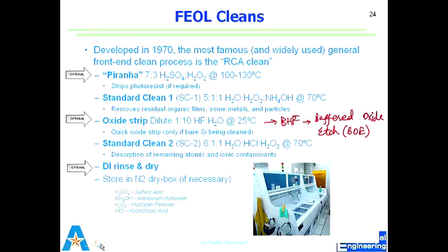To remove oxide, we use, as I said before, BHF. It's also called BOE, buffered oxide etch. Remember always, whenever I say oxide is going to be removed, the simple thing is BHF. Its etch rate is normally 1000 angstroms per minute. How many nanometers in 1 angstrom? 0.1. Start playing with these angstrom to nanometer to micron conversions, right? 10 raised to minus 6 is micron, 10 raised to minus 9 is nano, 10 raised to minus 10 is angstrom. So we use angstrom and nanometer alternatively.